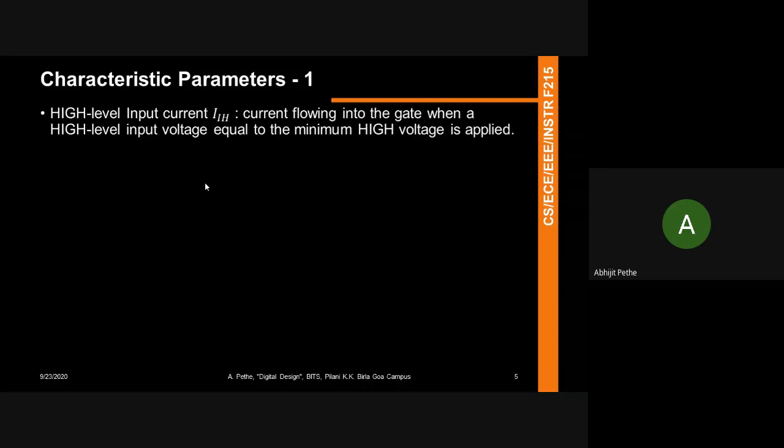The first thing to keep in mind is, whenever you say digital logic, we're going to talk about what happens at 0 and 1. And remember, 0 and 1 is for positive logic. When I discussed positive logic and negative logic, in reality what we're talking about is a low and a high. And this is purely voltage driven. We talk about two states of a gate: one is a high voltage, one is a low voltage. When we say positive logic, we map the high to 1 and the low to 0. If I'm using negative logic, then I would map the low to 1.